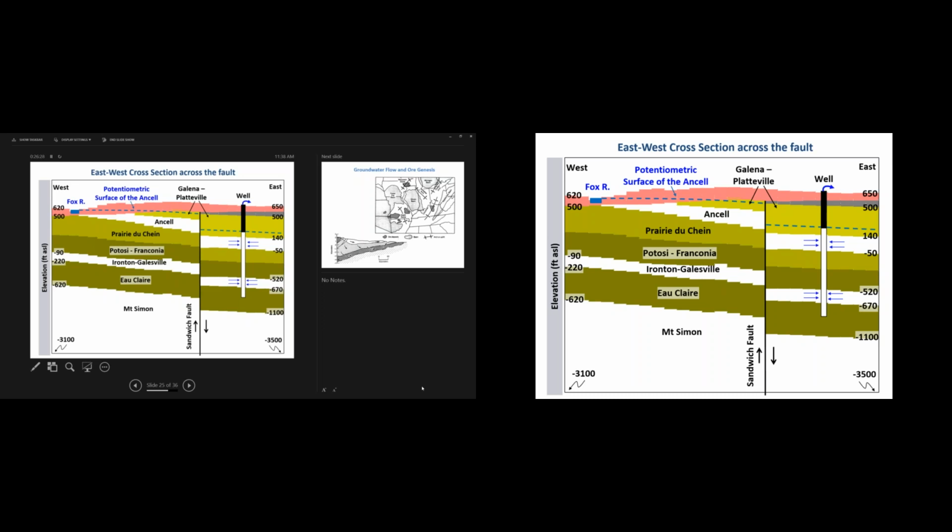So this elevation, if it's, say, 600, 610, and you have a 580 in here, whatever, say 680, sorry, those numbers don't even enter the calculation. It'll use them to figure out what the transmissivity is. Yeah, but then you have K, that value. Yeah, you can simplify the grid. Elevation isn't in Darcy's law anymore.